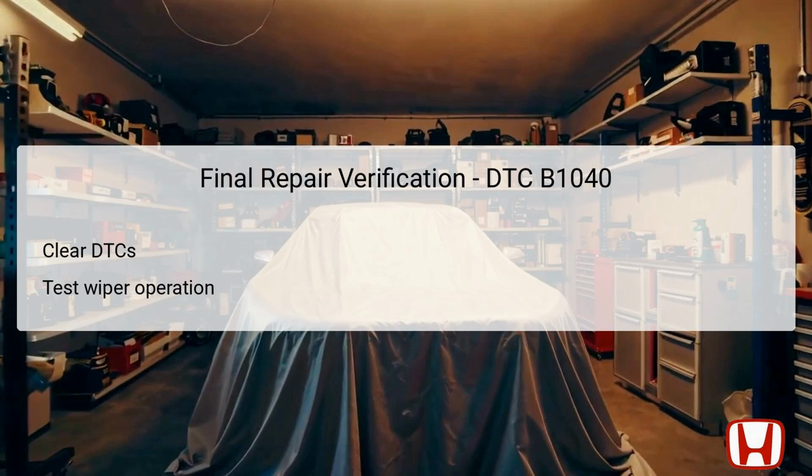Once the DTCs have been cleared, test the windshield wiper functionality by activating the wipers through their standard controls. Successful operation indicates that communication with the BCM has been restored and no further issues are detected. Verification is an important step, ensuring that the repairs made have fully addressed the problem, represented by DTC B1040.